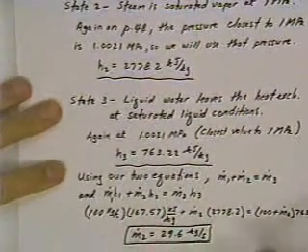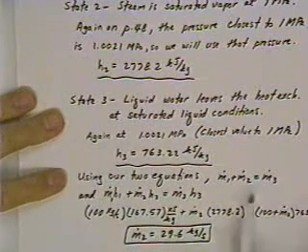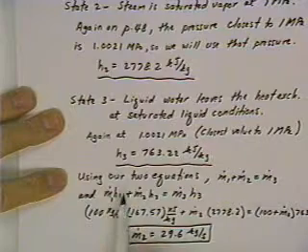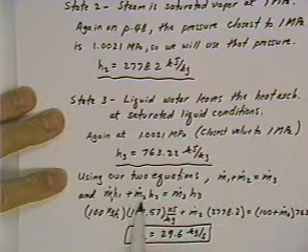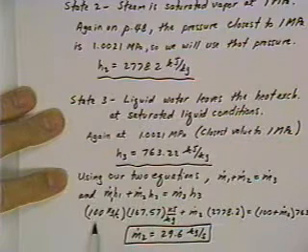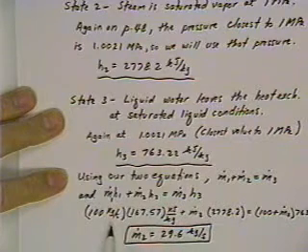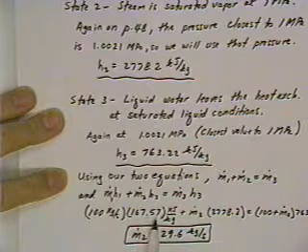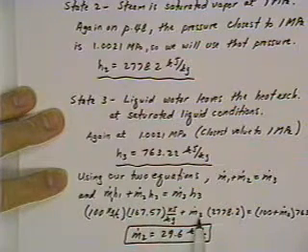Okay, conservation of mass equation then. We know that m.1 plus m.2 is equal to m.3, and we know that m.1 H1 plus m.2 H2 is equal to m.3 H3. So m.1 is 100 kilograms per second. Multiply that by the enthalpy of 1, which is 167.57. m.2 is unknown.